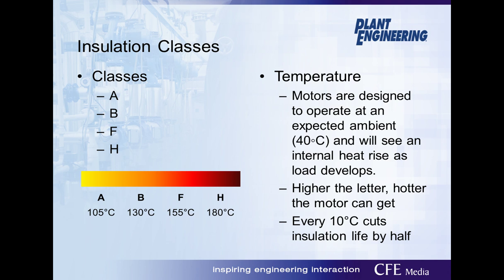Most motors will run much cooler than their insulation class rating, and a general rule of thumb in this industry is that for every 10 degrees Celsius of higher running temperature, your motor winding life will be cut in half. And just in case you haven't caught on yet, heat kills motors.